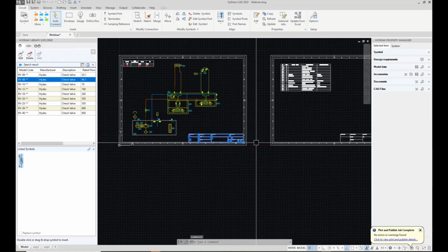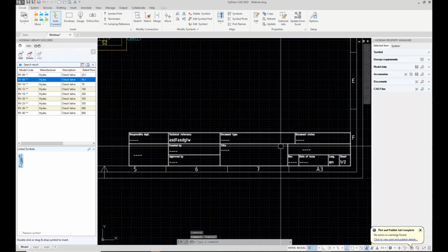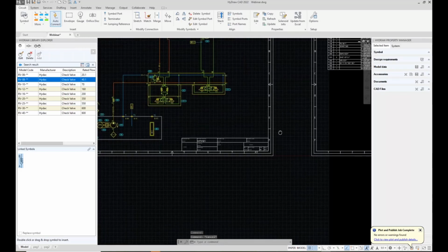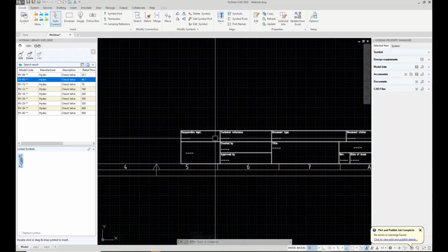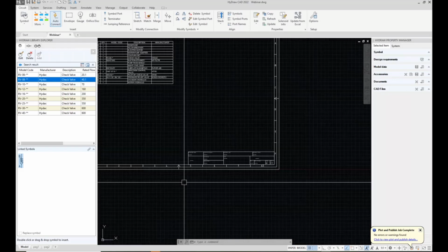A unique block name cannot have two different shapes unless you make dynamic blocks. With dynamic blocks, it is possible to create multi-shaped AutoCAD blocks. But in terms of attributes, yes, absolutely, you can edit the attribute, because the attribute is designed in a way that it does not replicate automatically on each title block.